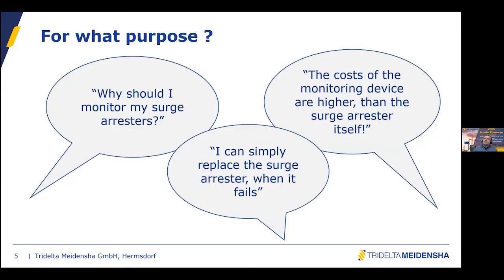As an introduction, we will start with some typical questions that we receive when we discuss monitoring with our clients, users and utilities. The main question is, why should I monitor my surge arresters? Does it make sense? Is it needed? There are a lot of utilities which are not monitoring their surge arresters. Another typical statement we get is, I can simply replace the surge arrester when it fails, I don't need to monitor. Of course, this is not exactly like that. The surge arrester is not a fuse.